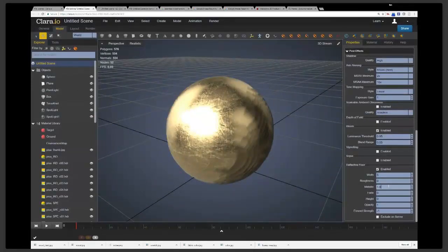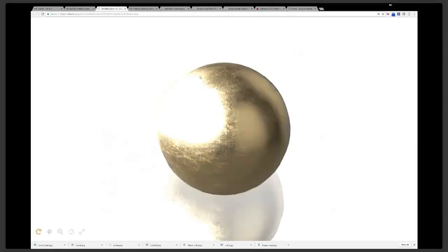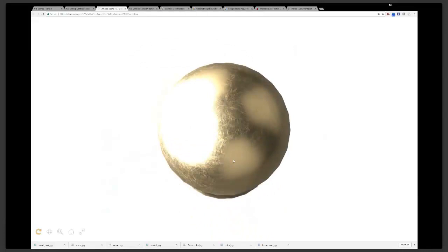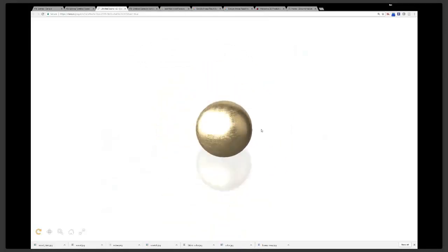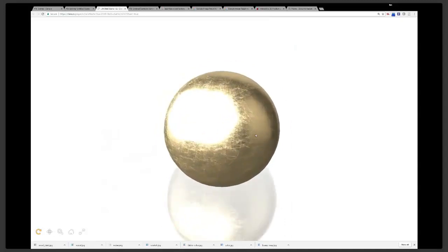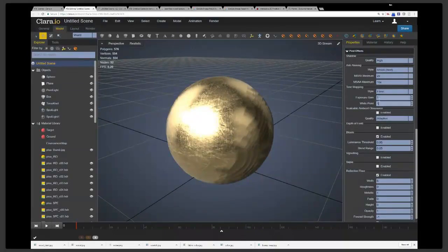If I want it really reflective, but still having that Fresnel effect, metalness of 1 here. And so now it's perfectly reflective when you're looking at it head on, and then it gets less as you come up. So that's some of the post effects there. And let's see. If I wanted to make this for a scene to show it off, I often use filmic tone mapping. You can read up on that on Wikipedia, but filmic 1.1 often looks quite nice.